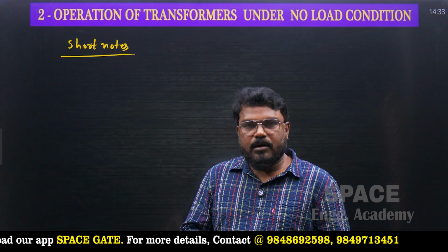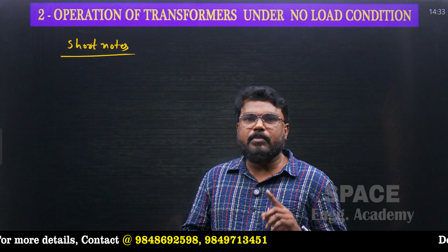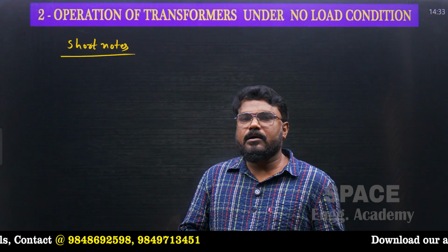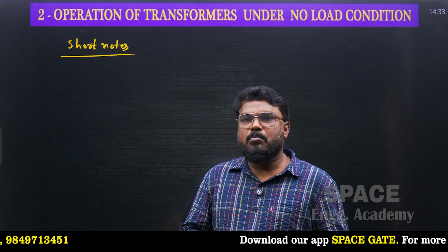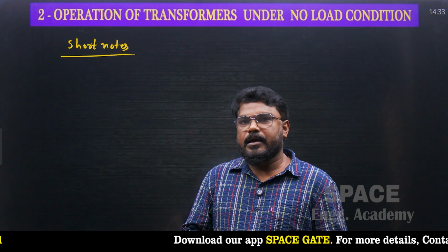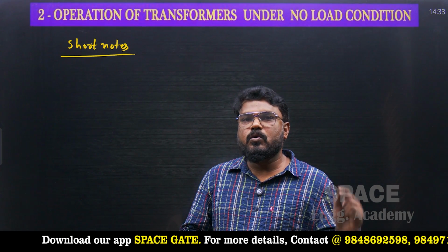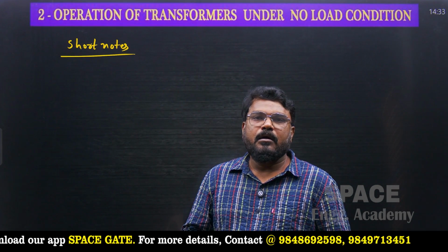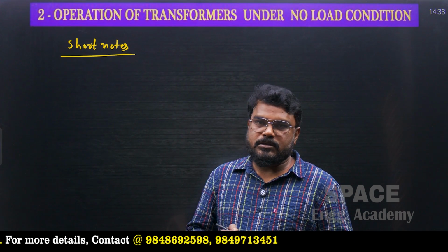First one, under no load condition, transformer draws two currents. One is magnetizing current and the second one is iron loss component of current. So the phasor sum of magnetizing current and iron loss component of current is known as the no load current of the transformer, and this current is also called exciting current of the transformer.